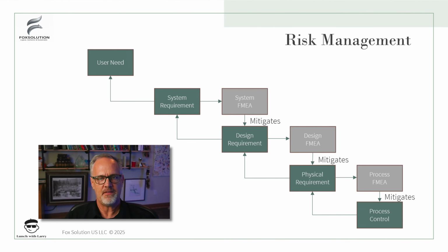So these FMEAs become part of the data model and explain from an occurrence standpoint how often some problem can occur to lead to a problem where the next level up isn't delivered. And so the nice thing about this is each one of those lines has an occurrence that's associated with it. So we can say what we believe the occurrence of some problem is going to be.